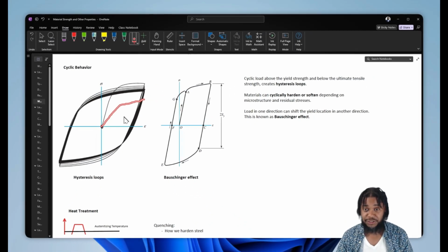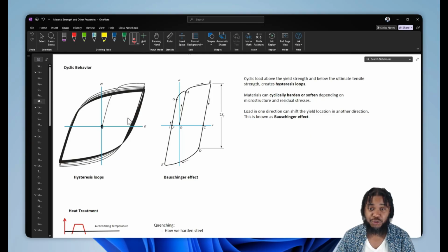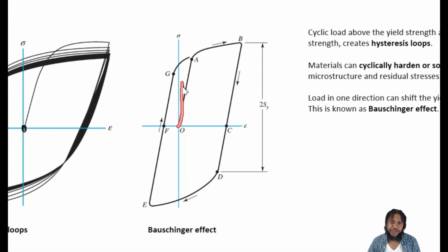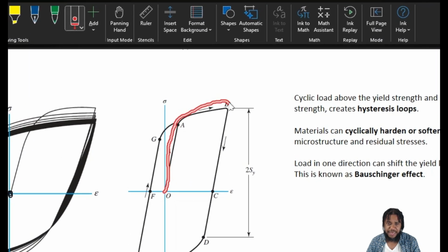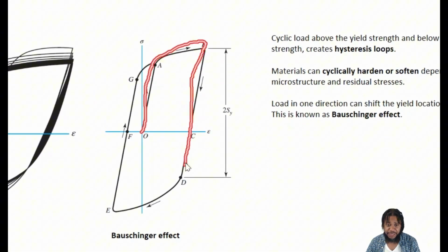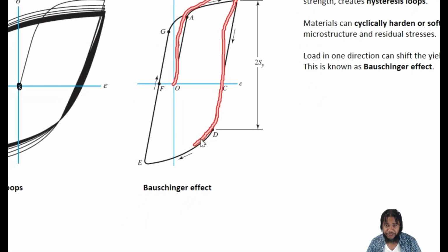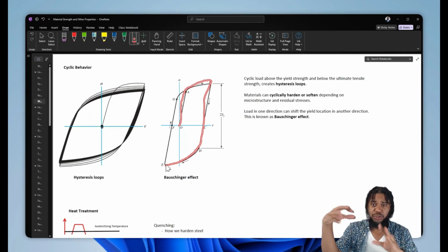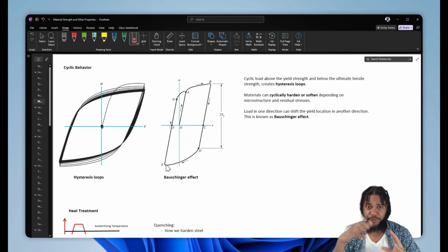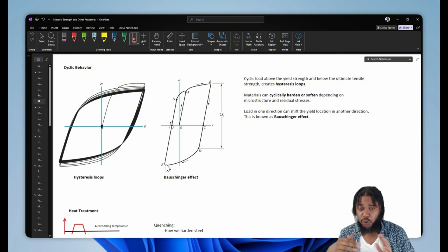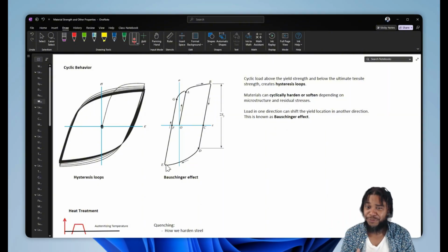They are less resistant, with less stress to get the same amount of strain. We also can find in some materials that they have an asymmetry in their yield behavior. If you were to go through yield in tension first, and then you come around in compression, it will yield at lower stresses in compression because the whole yield surface has shifted. Your material, because of all that cold working you did in tension, is less resilient in compression, right?